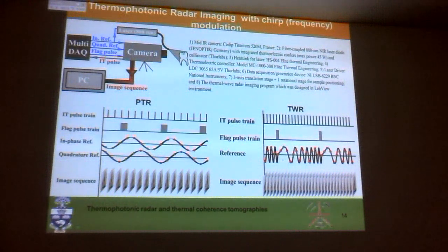But typically, I'd say 30, 50, 60 hertz, you can do now. You can do undersampling. That's the other thing you can do. Instead of sampling every cycle twice or 4 times, you do one cycle, you skip another one. So your frequency is still low, but you're going from 0 phase to 90-degree phase, not over the same cycle, but you skip one to the next one. That's undersampling. The third cycle is going to be the 180 degrees and so on. That allows you to still keep the frequency low. But if you do too much undersampling, then there is a jitter coming in later on. So the field starts becoming a bit fuzzy if you do too much undersampling. So there's only so much you can do.